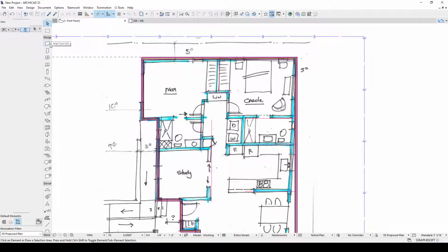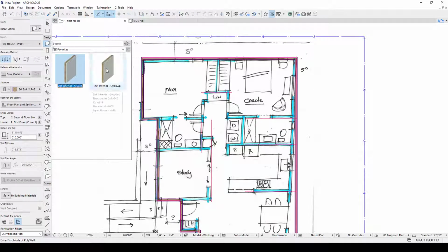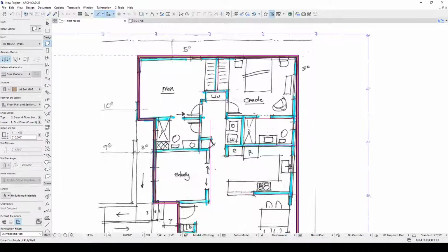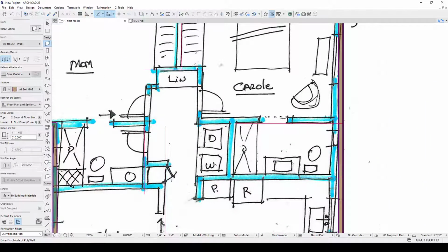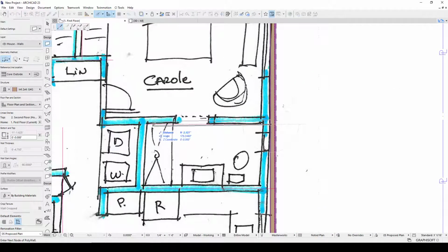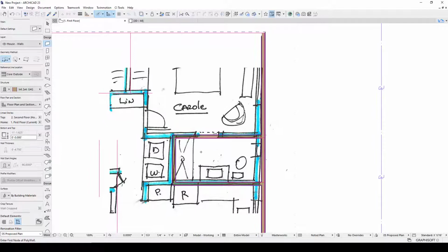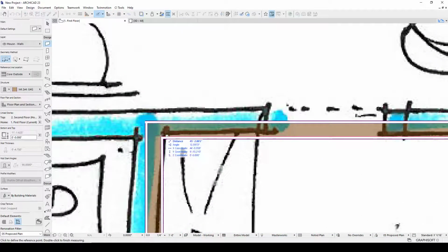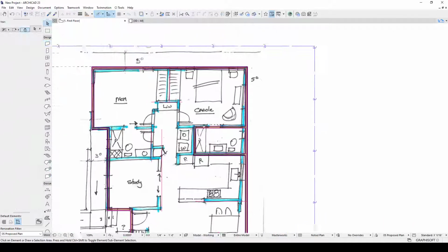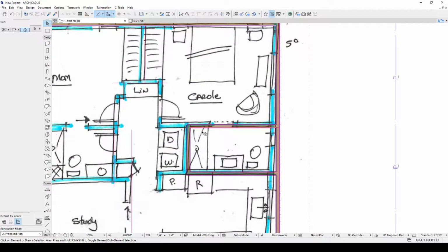And now we need to be careful to switch our wall type to an interior. No plywoods, just an interior 2x4. Core outside. Now there is no inside and outside, they're interior walls. But we do want to make sure the wall's on the correct side. So here I can come in and put this bathroom. I know I want that to be exactly 5 feet, stud to stud. Some people like to do 5'.125". I'm going to leave it at 5 feet.